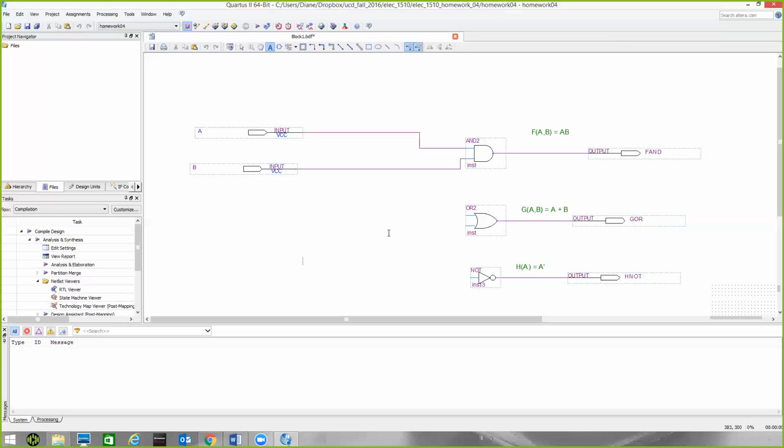Right. Now, I don't need to draw two other input pins. As a matter of fact, if I were to put another input pin on here and label it A, I would get an error. What I can do is wire this to A. And I need to turn off my text tool. Notice that's still highlighted, so let me go back to my selector. I'm just going to bring this down here, crosshair here, hold, drag, and go to A, and I clicked to get rid of the blue. So this little dot means that's a junction. That means this wire is now connected to A.